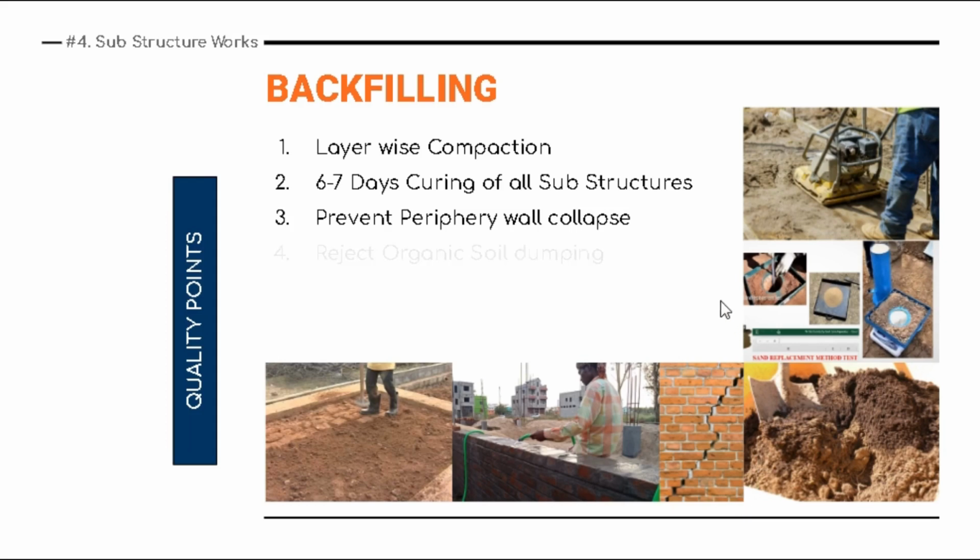Then, no organic soil dumping in backfilling soil. Never use this, because organic soil has an expansive property. I have said this before as well. You need to be very careful. Never allow organic soil to be brought in for backfilling purposes. Maybe 90% of the time the contractor or the vendor will say that it's just for backfilling, use it, no issue. So it is dangerous, so always disallow that.